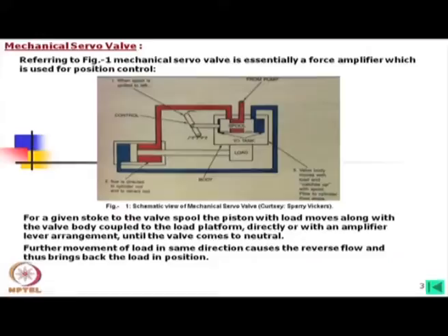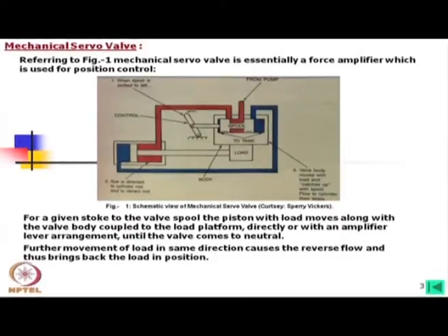Thus, not only is this position control maintained, that means constant velocity will be maintained. Now, this happens together. If there is no sensor, of course, then there is a possibility of drift, that means after some time it may not match. Actually, there will be positioning sensors, and along with that there will be some corrections, which is called feedback control, to the input side also. However, if you remove this input, then it will be again in this standstill position.